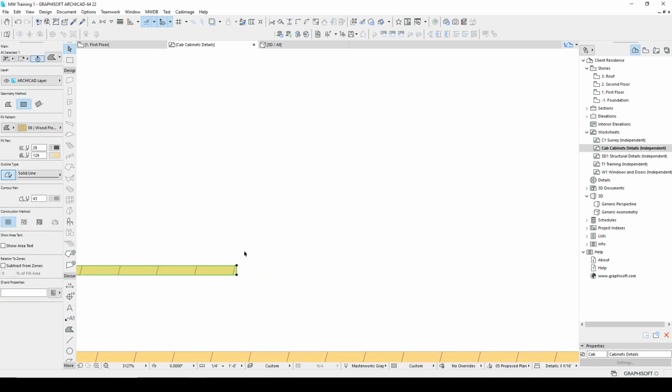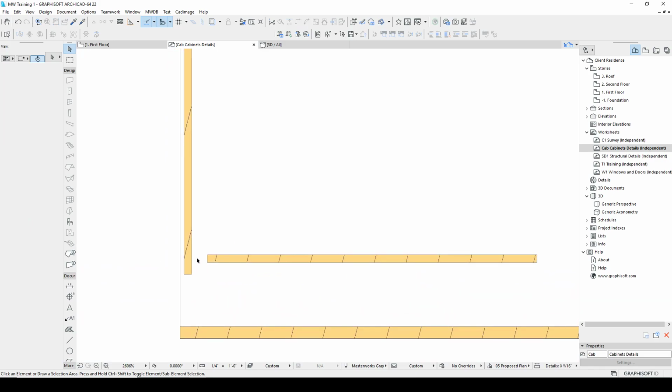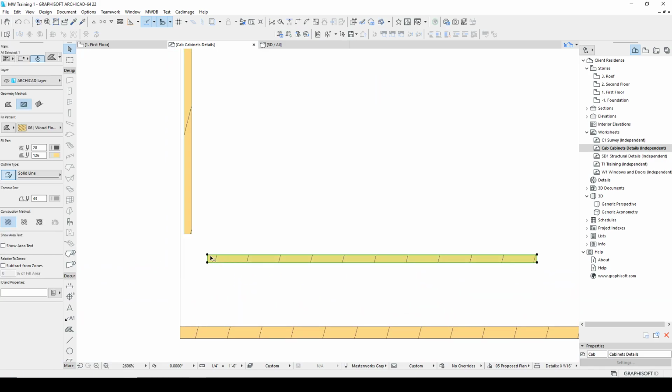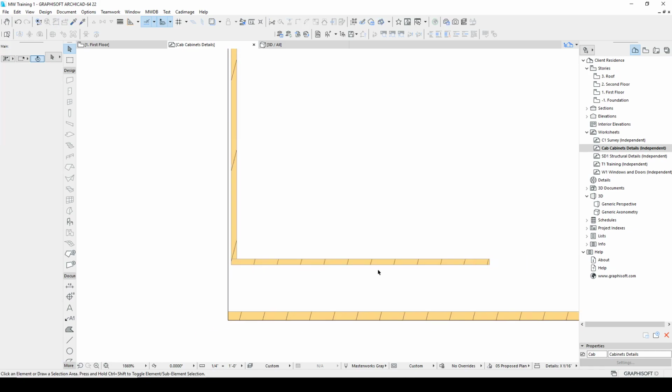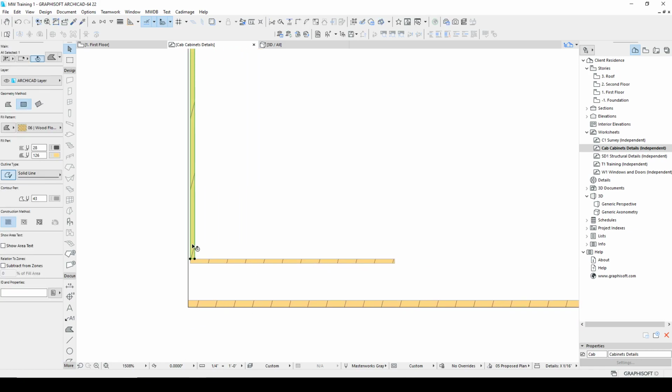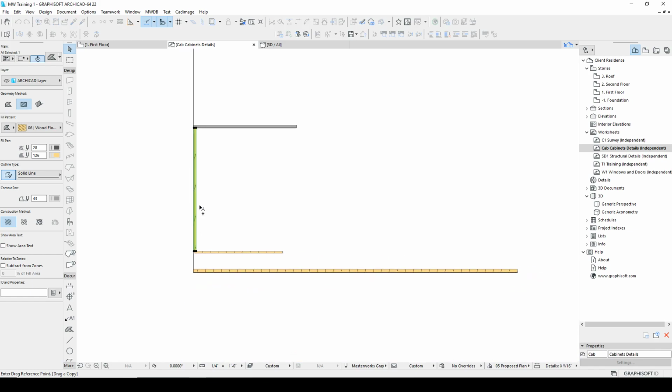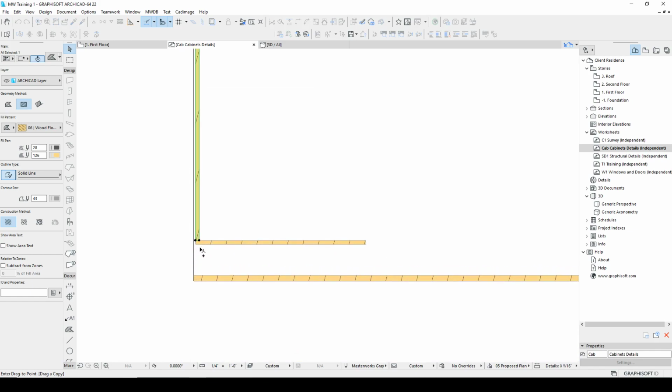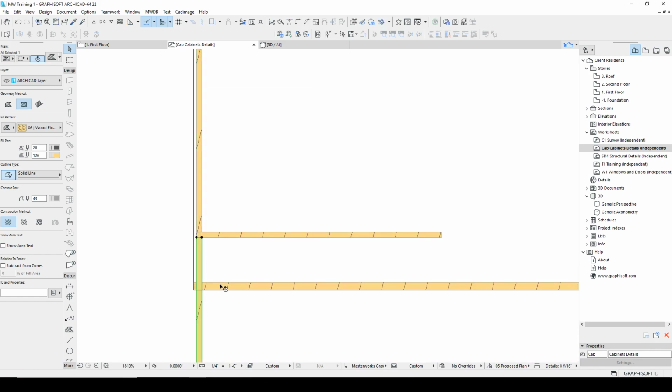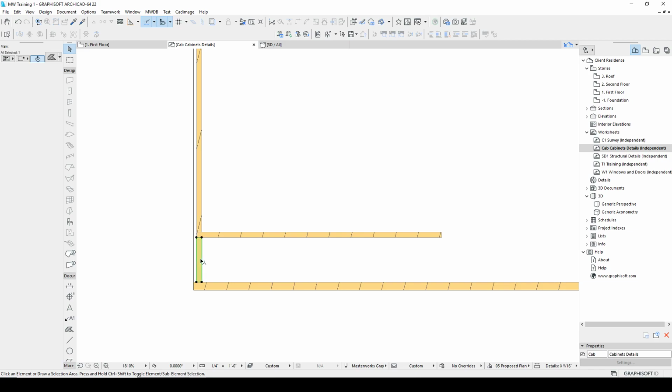So this is my cabinet box, my toe kick is below that, and then you can just begin to make sense of all this. So I'm going to take this and F9. I'm going to copy from the top straight down. I'm going to use S, which is for slice. Then I need a cutting line, and then select the side I want to select, or click on the side I want to select. Then I can just delete that.